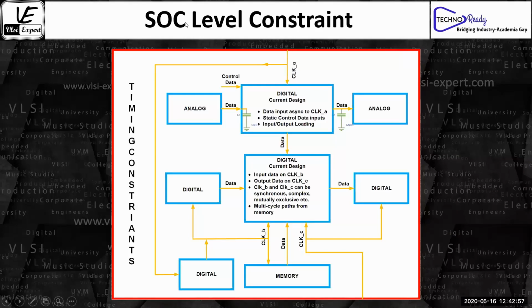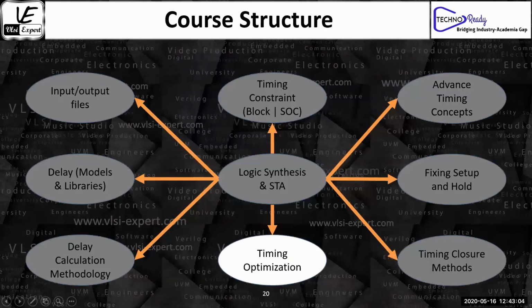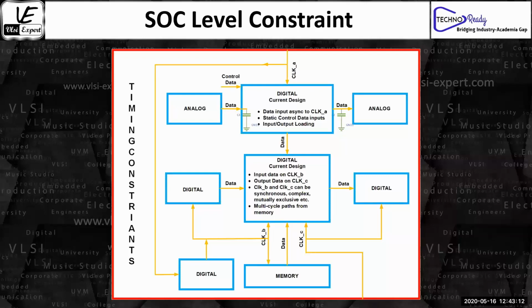If they are coming from the same PLL, they are synchronous, but there will be uncertainty, jitter, and skew associated with them. What are the margins? How do you specify those margins? If they are asynchronous, we won't write any constraint for that. Actually, we'll define those paths as false paths. You're right, but that may or may not be true. So it depends. You try to specify clock domain crossing, such as the time delay between the two timing logic cones. But you're right, if it is asynchronous, then you try to just define it as a false path. But that is only a very small part of what we are trying to say. There are a bunch of other combinations possible. But a very good question.